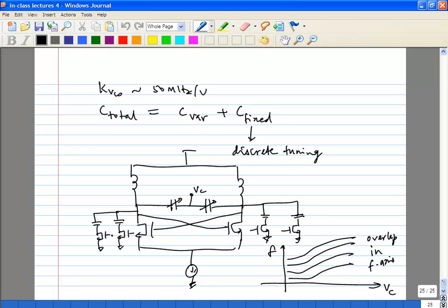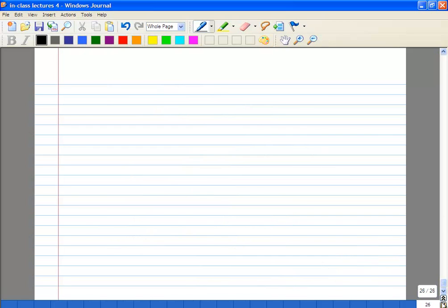The other thing you have to remember is, obviously, as you go from lower frequencies to higher frequencies, your KVCO will change. In one case you have larger capacitance, in the other case you have less fixed capacitance, so definitely your KVCO will vary, because you're going to have a different number of fixed capacitances on and off. So you're going to make sure you try to restrict it to within what your PLL can withstand.